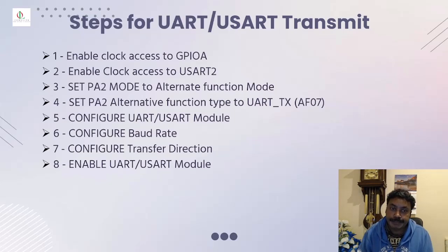So when you say PA2, what does that stand for? I'm sure most of you would know by now. It is nothing but port A and pin 2. So you got to set port A and pin 2 to alternate function mode. I'll tell you why we are learning only PA2 today in the next slides.